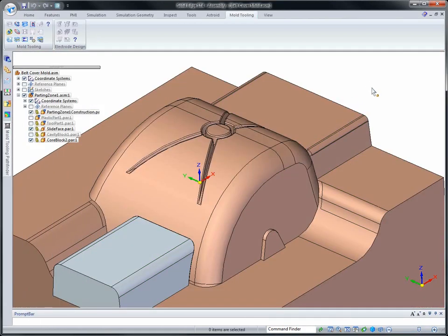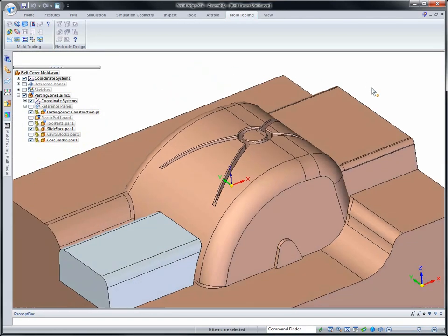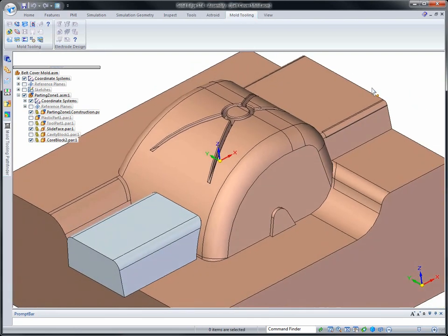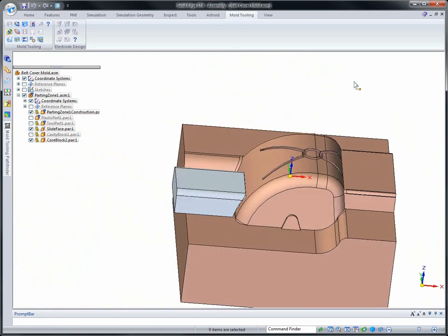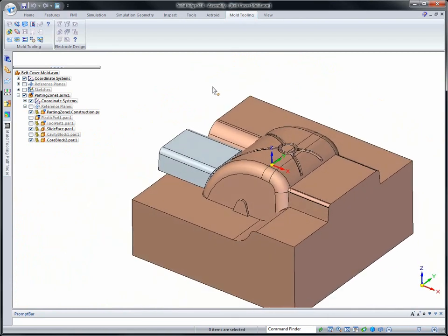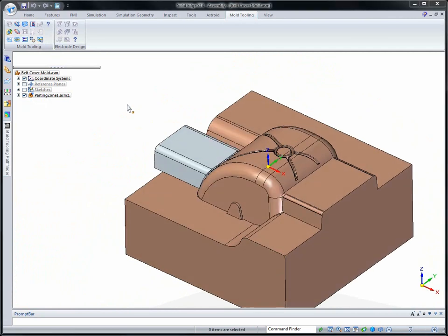Okay, so you have a nice smooth surface. You can see the inserted area where we got rid of that U shape going out the entire part. We could put an insert in there to create that, which again would be much more machinable. Next step then is to define this as a 4-cavity mold. So what we want to do is pattern our core cavity set.